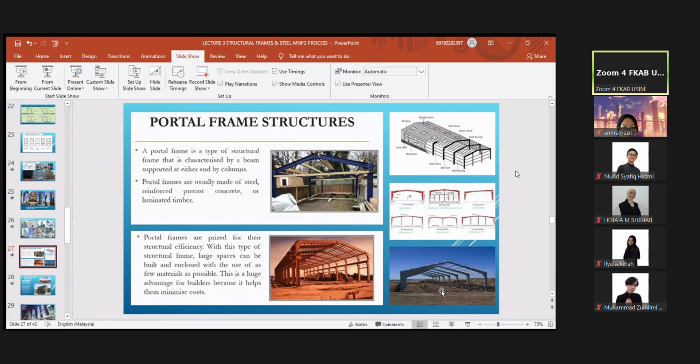Similar for this one. Of course, the engineer has to design whether to maintain this as a uniform size, or whether to widen the beam, as the load is very small here. The load is still coming here and transferring to this. Maybe the beam is tapered in response to the load structure. Here it's tapered in response to the load structure. This is less load. It goes in and the column takes the whole load.